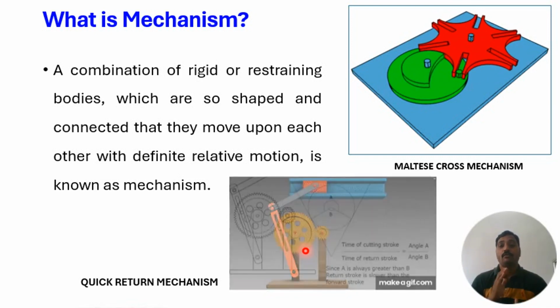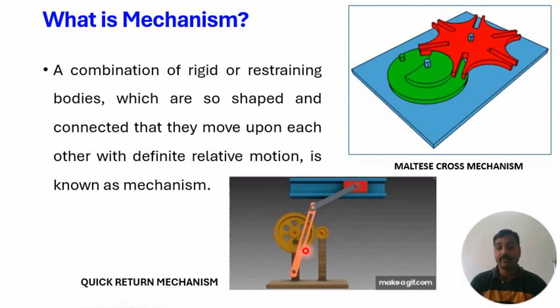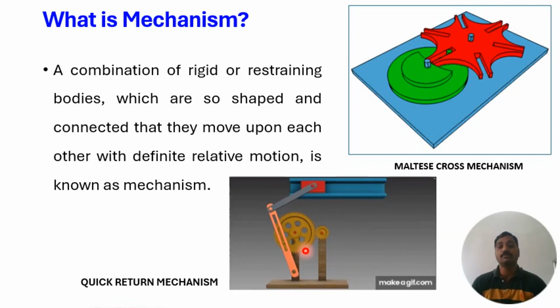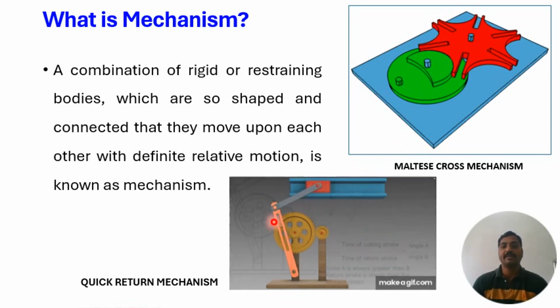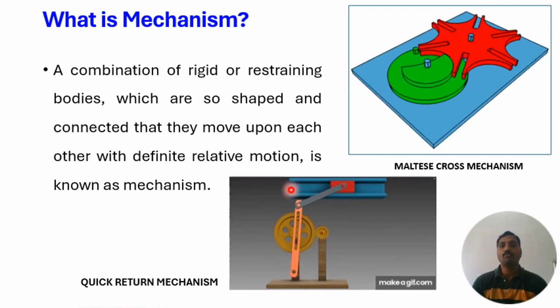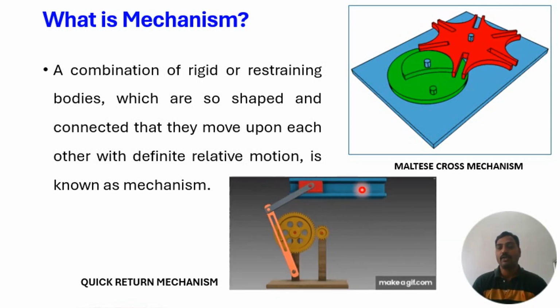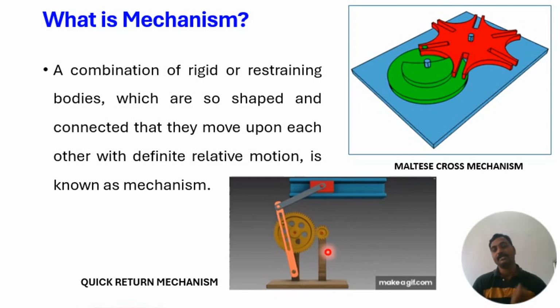In this case, the forward stroke is used to cut the unwanted material from the stock bar, and the return stroke must be fast. So we use that mechanism here. There is a bull gear system, a slotted crank lever mechanism connecting, and a slider. You can see the slider moving in the slider guideways, because of the relative motions created by these kinds of mechanisms.